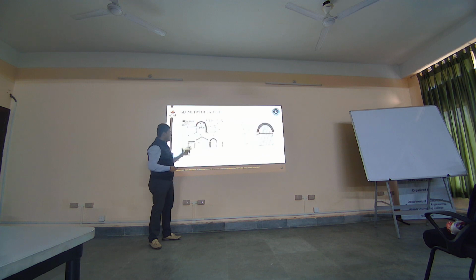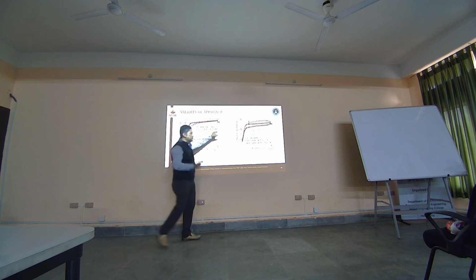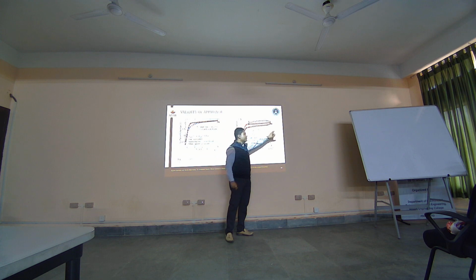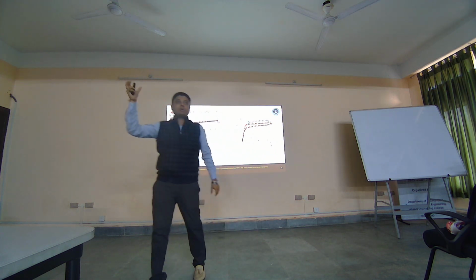After that, we went for boundary condition matching for two structures, and then we inserted it. We got this. So we were very happy because we had already developed the model. But now, if you are going to report this, you'll also have to show for other voltages. So when we went for higher gate voltage, you have this mismatch. So it means there was something in the gate voltage part where you have to tweak your boundary condition.